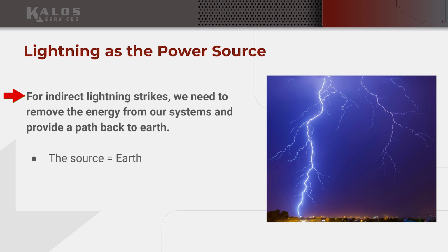This is why it's good practice to install this grounding electrode conductor system as close as possible to the point of service. And now code actually requires us to install that grounding electrode conductor at the main service disconnect. There's a good reason for that: so we can get that lightning energy from the utility, which might come in on the utility lines, out of our systems as quickly as possible. Right. I talked about that longer than I probably should have.